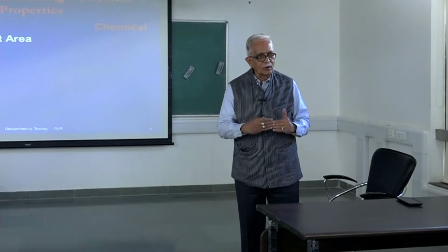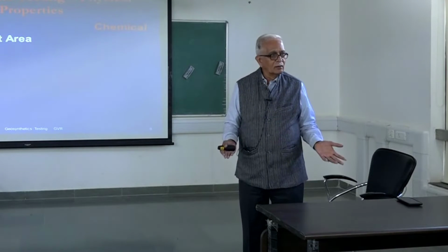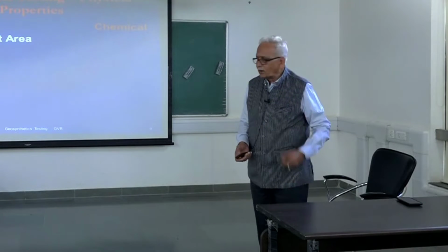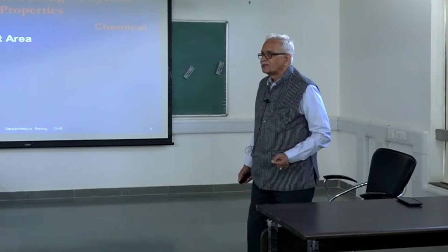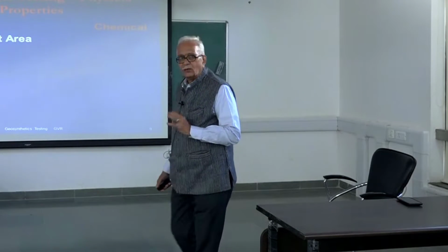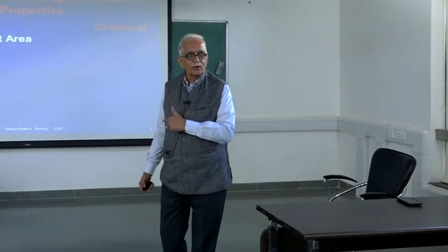So it tells us, normal D10 will give us some idea of the soil which we are going to think of. Same thing here, there is some apparent opening size we will define clearly. So actually these 3 are some of the most important characteristics, and exactly like our liquid limit and plastic limit, they will tell you all about it. We may not use them in direct design also. We may use only the AOS,